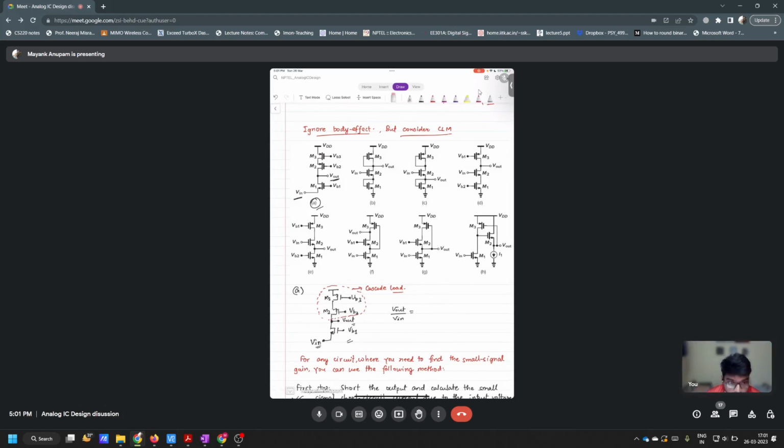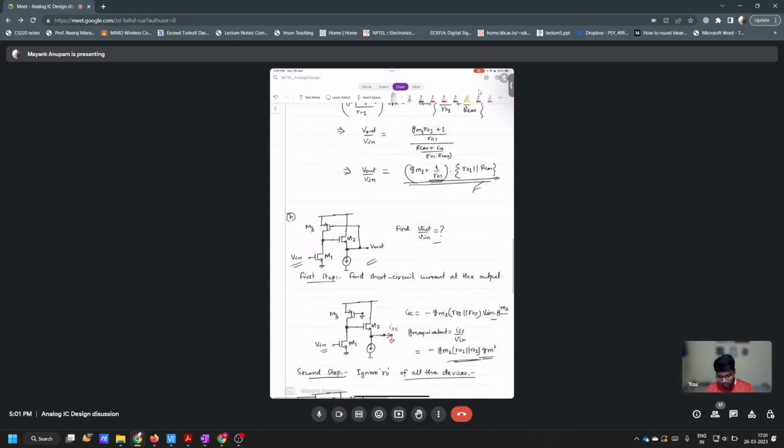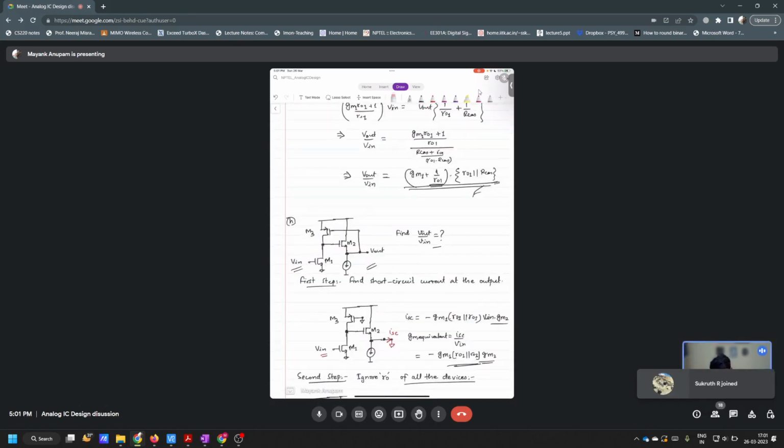Sir, one doubt regarding the negative feedback. Vout increases, so ID of M3 decreases, so VD of M3 also decreases. Correct.